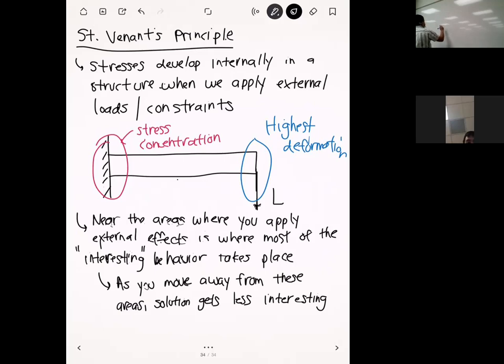If we consider this point, it has the support of all the material down here and all the material up here. And so that's why the stress here isn't that big. But if we consider a point right here, because this is a stress-free boundary condition down here, you don't have any supports down here to help distribute that load. And so in order for this specific point to be in static equilibrium, if we slice this material like this, the internal stress has to be relatively high compared to everything else. Exactly. Oh, that makes sense.